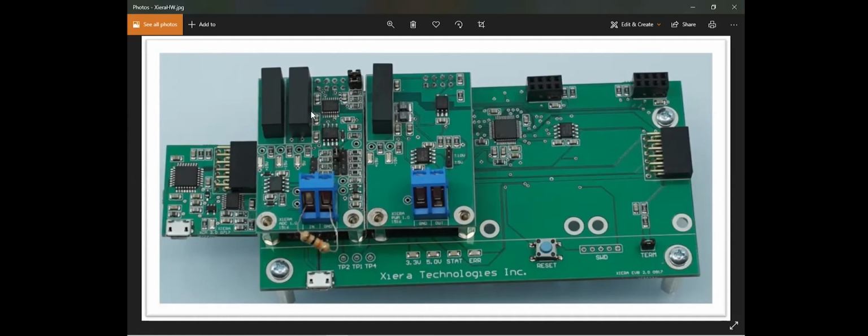So what the user can do is use this small EVB here to very quickly and cheaply connect to their system, take measurements for data acquisition, create their model, tune the fuzzy loop, and then test it directly using our hardware without having to develop their own prototype. Of course, if you already have an existing application or prototype, let's say you have an SBC or another system where you can get I/O data already, and you can interface with your process, then you're more than welcome to just directly integrate the small controller board.